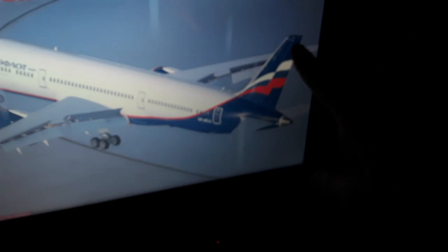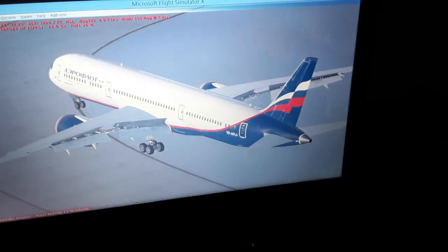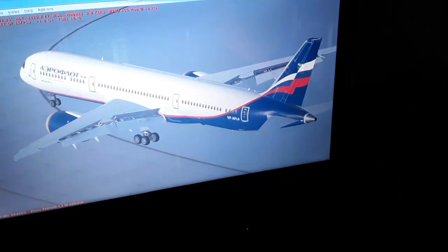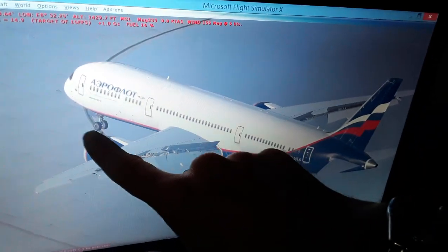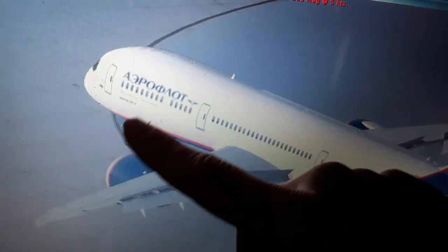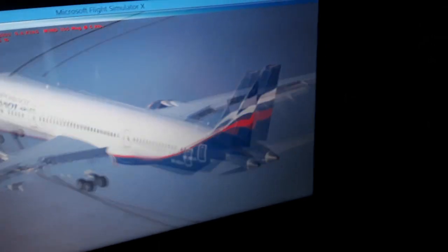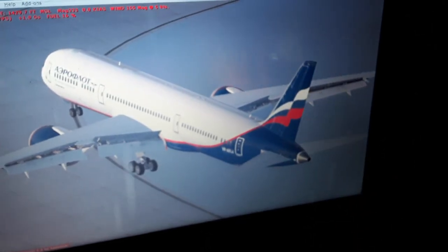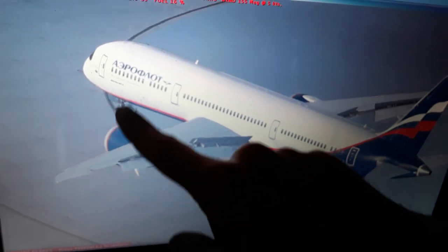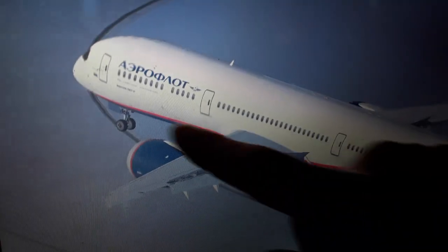Then at 45 knots the rudder becomes aerodynamically effective, above 45 knots, or about 70 kilometers an hour in takeoff. So we have the rudder aerodynamically effective at 45 knots, 70 kilometers an hour, and the deflection of the nose wheel decreases from 76 degrees to about 7.6 degrees at 80 knots, or 144 kilometers an hour. Then we have only the rudder aerodynamically effective, and vice versa as we land. So the nose wheel is deactivated and deflects to the 0 position.